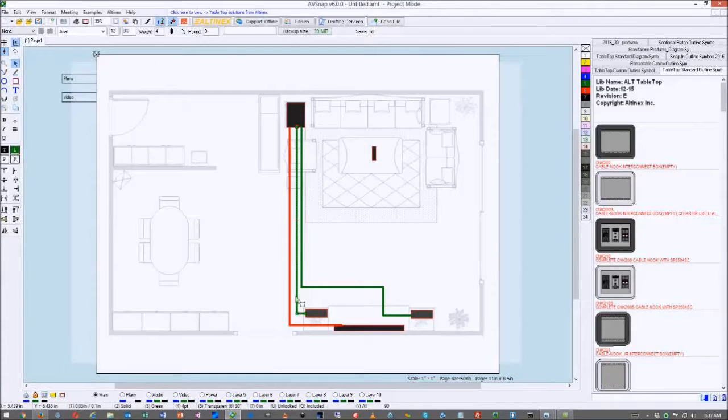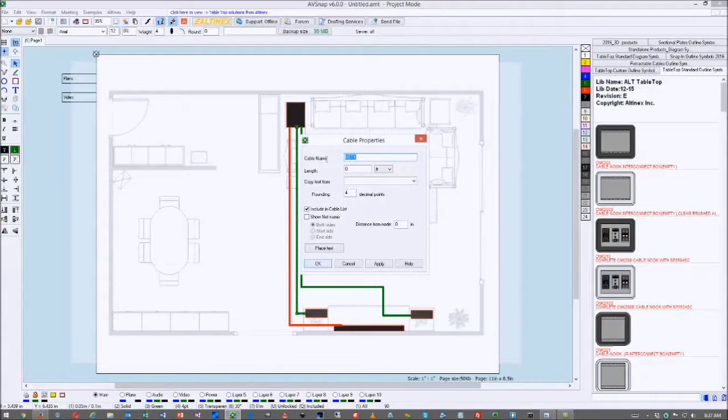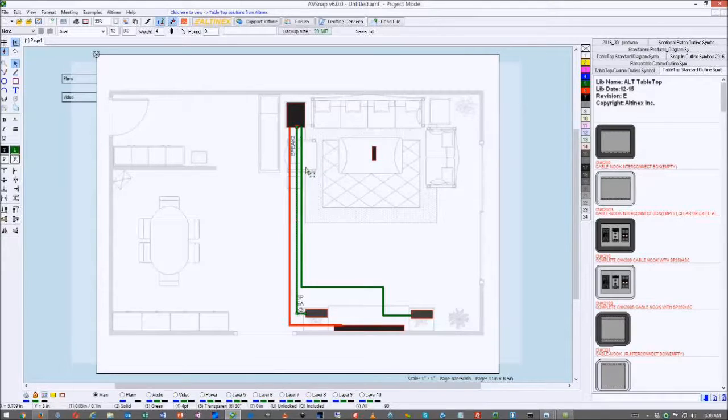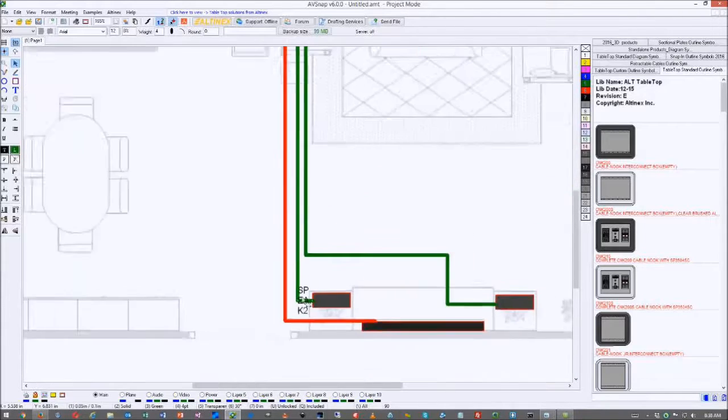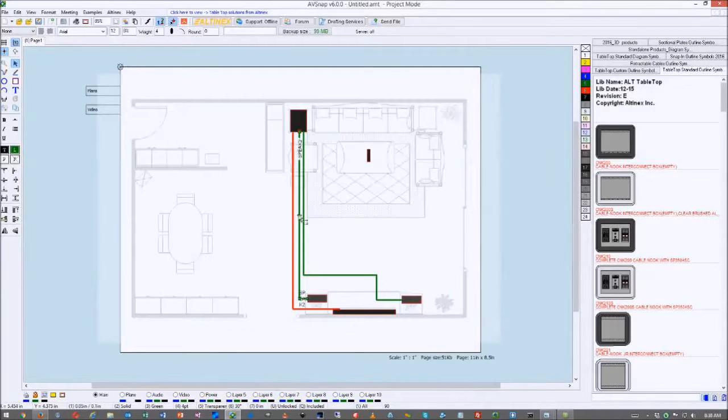And property by pressing letter K on the keyboard. If you want it to show on both sides, you can just show it on both sides and adjust it vertically so that it stays right with the cable. Now you see there's a little bit small space here, so it's hard to see it, so you can always move it out a little bit to the left, and you can also adjust the size of the text to make it smaller, okay? Or increase the line here.